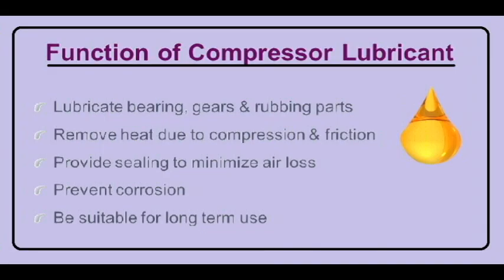Function of compressor lubricant. Lubricate bearings, gears and rubbing parts. Remove heat due to compression and friction. Provide sealing to minimize air loss. Prevent corrosion. Be suitable for long-term use.